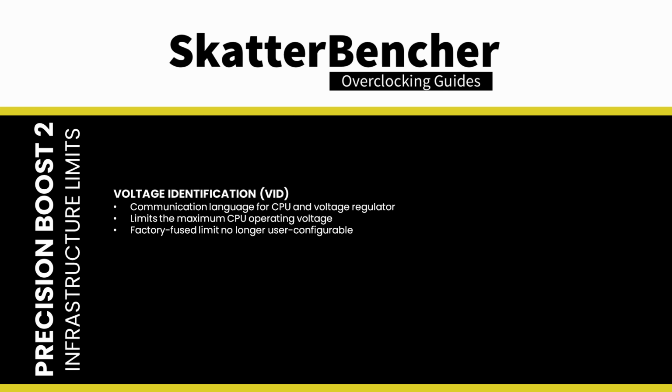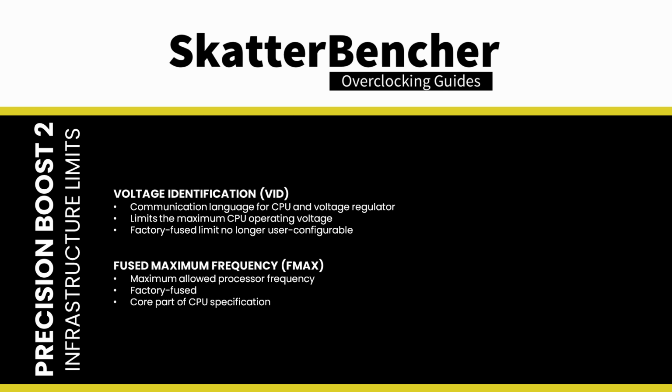Voltage identification, or VID, is a way for the CPU and voltage controller to communicate voltage requests. The VID limit is the maximum allowed voltage for the processor. The VID limit is factory fused and cannot be changed by the end user anymore. Fused maximum frequency, or Fmax, is the maximum allowed processor frequency. This value is fused from the factory and is obviously a core part of the CPU specification.